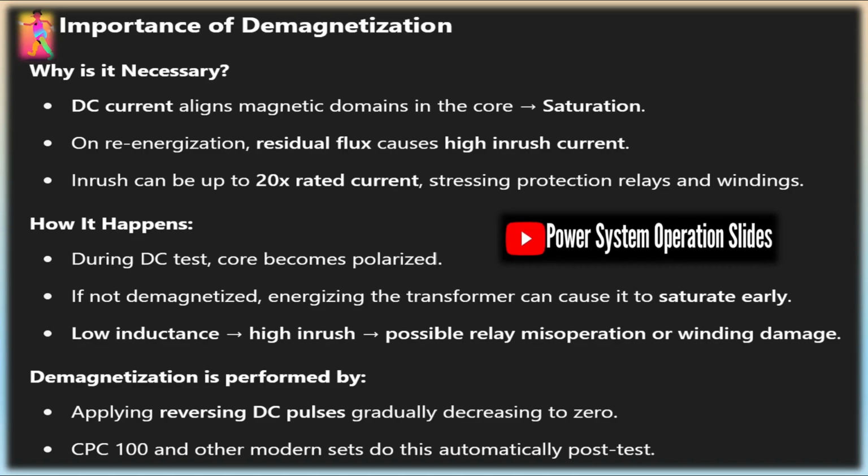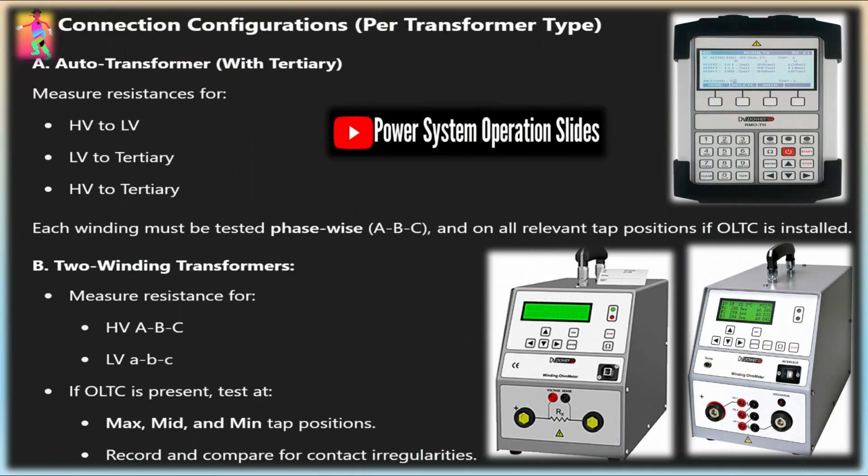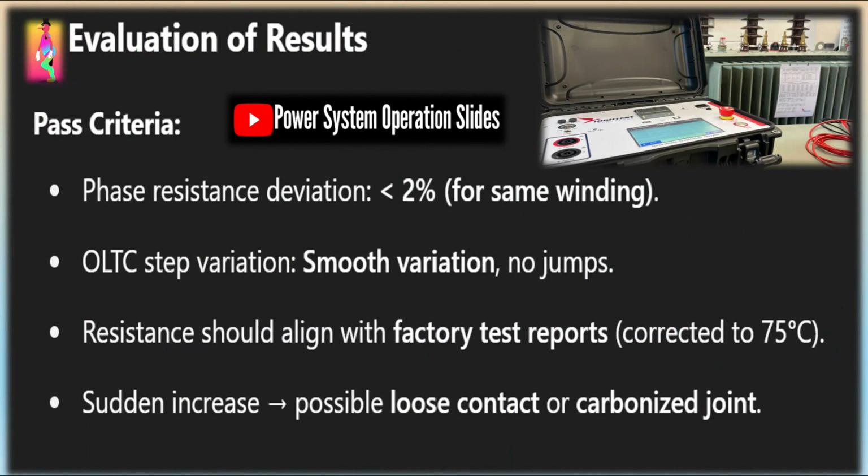Abnormally high resistance values may indicate loose connections at the winding joints, while lower than expected values can suggest shorted turns within the coil. Both conditions, if left unattended, can lead to localized heating and accelerated deterioration of insulation materials. Early identification of such anomalies allows for maintenance interventions to be planned with precision and minimal impact on system availability. This methodology plays a critical role in ensuring a stable and reliable supply of electrical energy across the network.